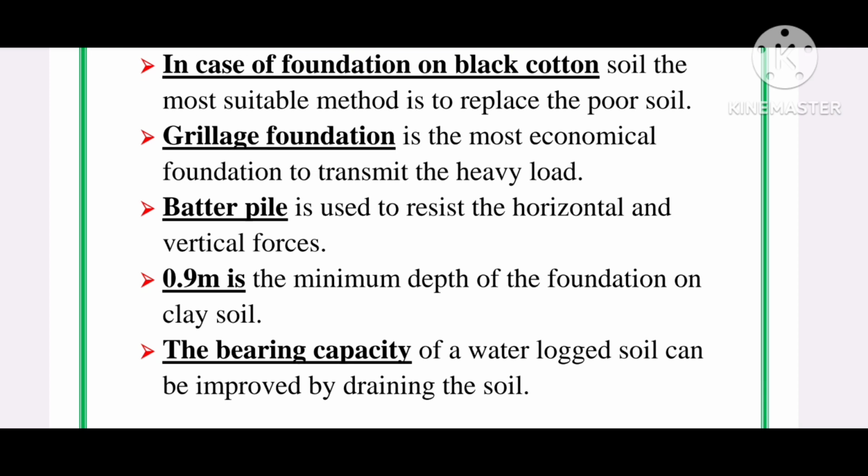0.9 meter is the minimum depth of foundation on clayey soil. The bearing capacity of a waterlogged soil can be improved by improving the drainage of the soil.